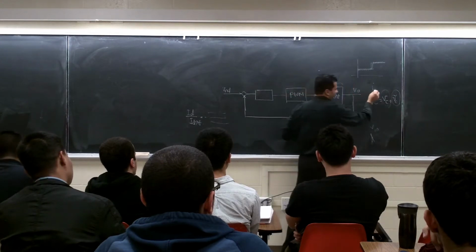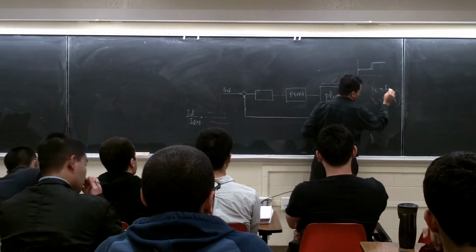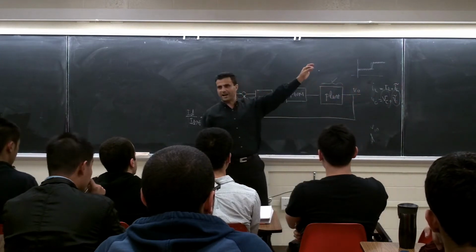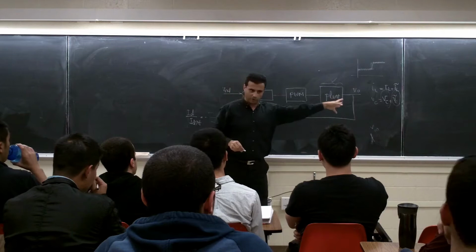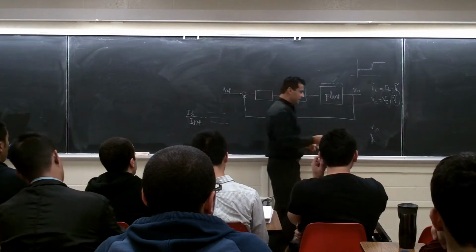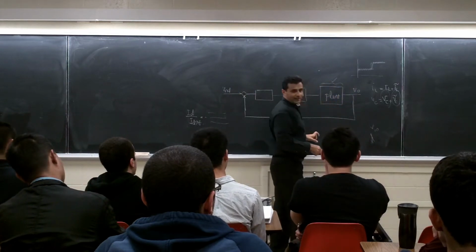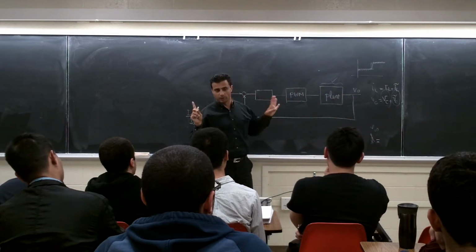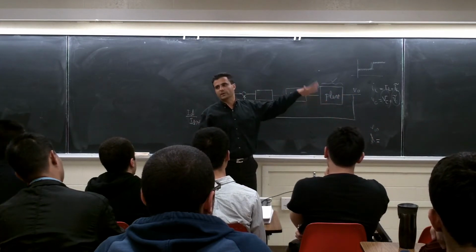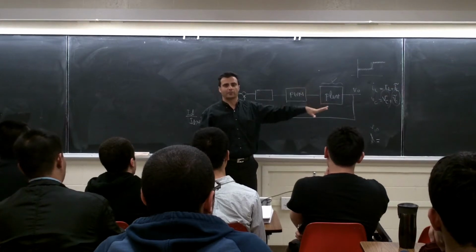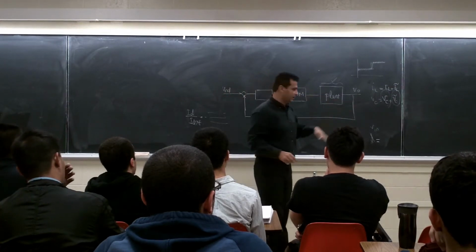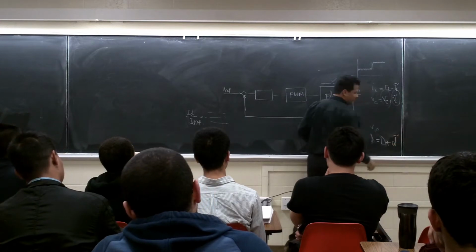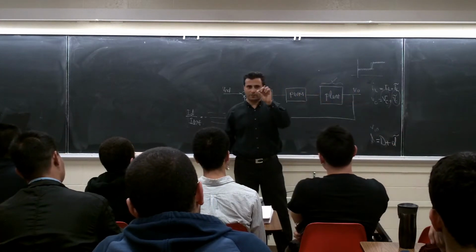For example, IL, again, is going to be IL plus IL tilde, right? It's going to have a DC value plus a ripple. We call it IL tilde. D, even D, if you look at it, D is going to be in the control loop, closed loop control, not the open loop. In the open loop, you set a D of 0.8, I don't know, 0.7, 0.5, right? So it's a fixed number. But in the real system, in the control system, if you look at your D, D is going to go up and down, up and down.